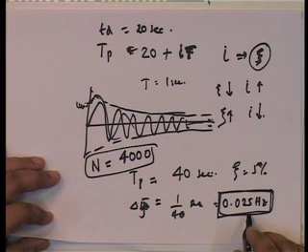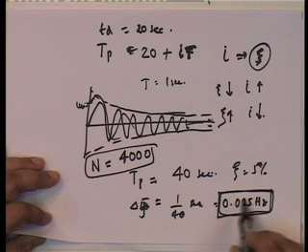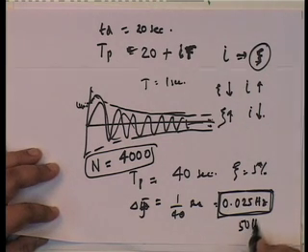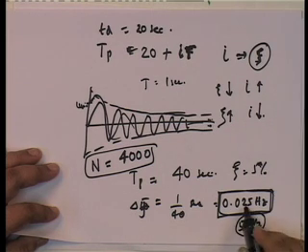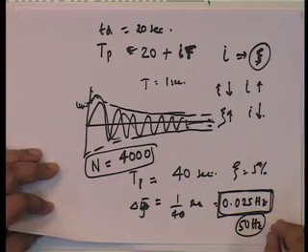Well, what is the Nyquist frequency? Well, we know delta t is 0.01. It basically means the Nyquist frequency is 50 hertz. 50 hertz, 2000 points and minus 2000 points, that makes it 4000 points. So, you see how the entire thing matches up.